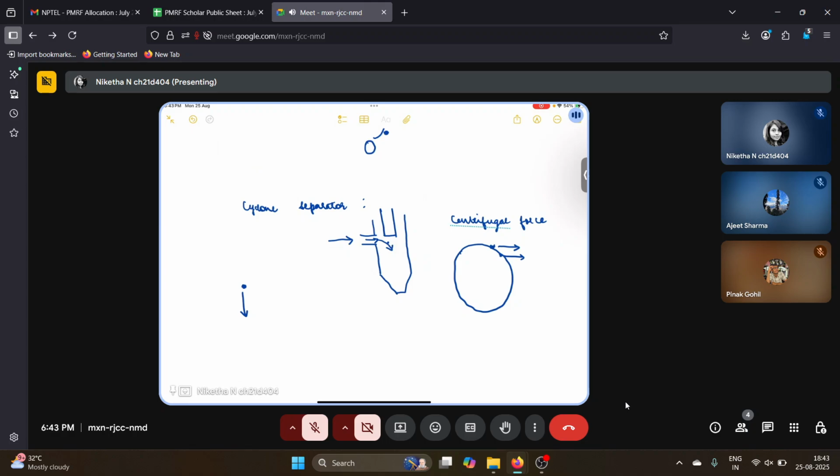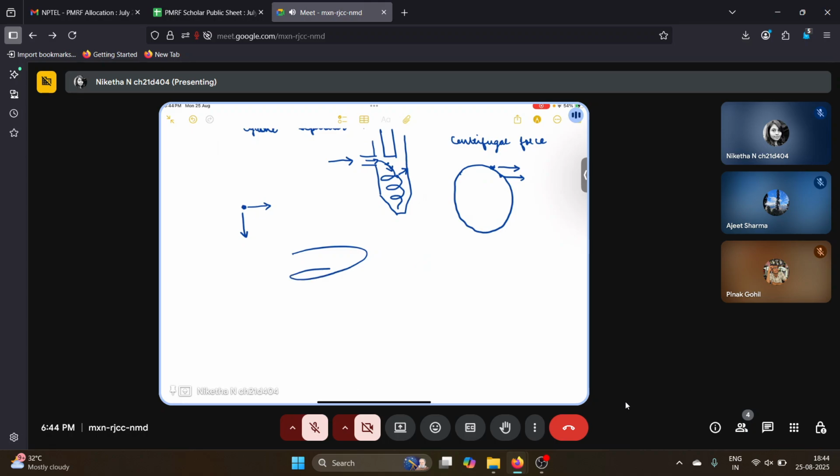But because the wind is entering into a circular motion like this, as the particle passes through these circles, there is centrifugal force acting on it, which makes the particle move sideways from its path. So if your particle is here, moving sideways means moving away from the circular path towards the container. It's like the wind is acting like this, and your particles are moving sideways.